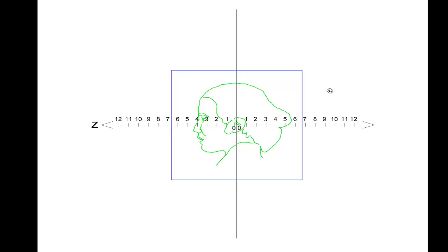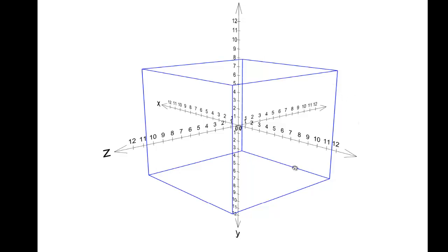Now, in our next view, let's put these all together. We can put this inside a cube. You may have already had this information, I'm sure, if you've taken any drafting in high school or other technology type aspects of drafting. We talk about this as the drawing cube, and it has 6 planes of projection. It has a front, a right side, a left side, a back, a top, and a bottom. 1, 2, 3, 4, 5, 6.